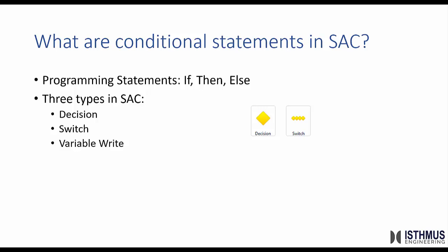And then the one that is very rarely used, but probably should be used a lot more, is a variable write, where basically you can write an if-then statement using Visual Basic as the language, and define a variable to be whatever you want it to be inside Subassembly Composer. It's actually a very powerful way to do stuff that has a lot of different options associated with it. We are going to save that one for the end. It's a little more complicated and a little more nuanced. So if we get to that, that means we're doing good on time.